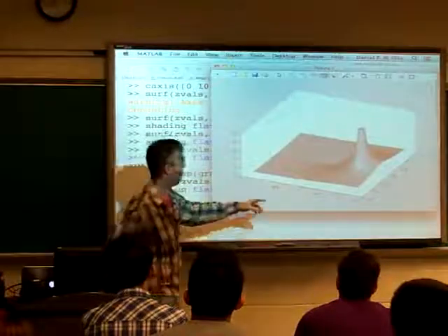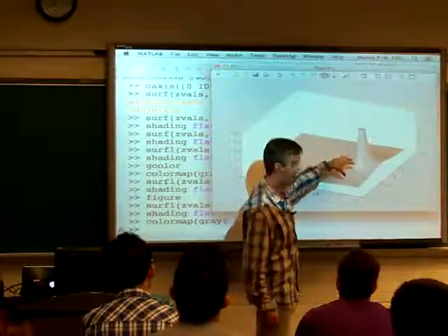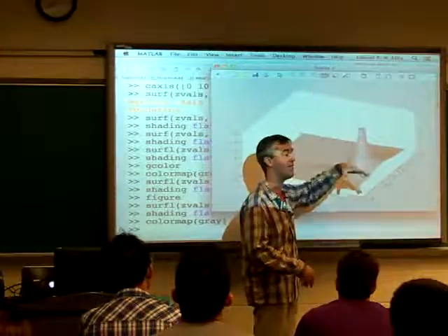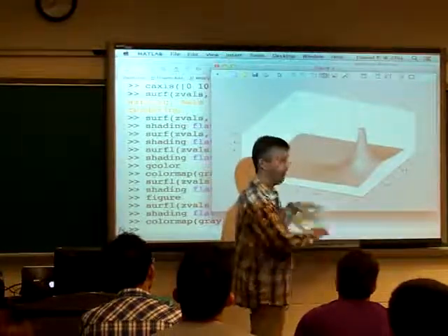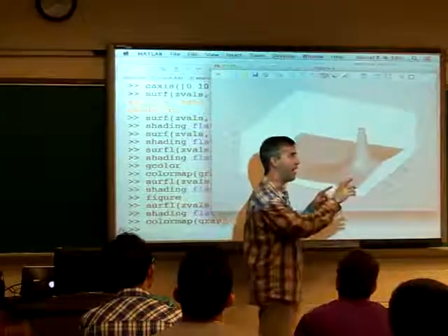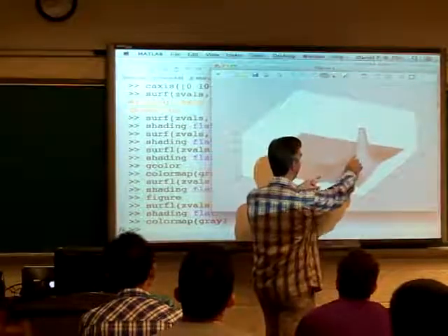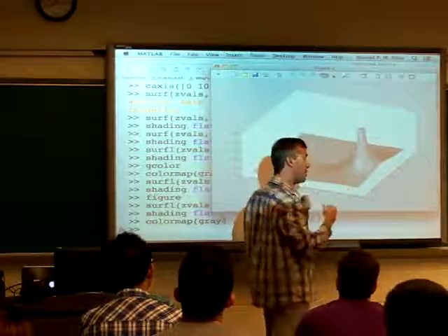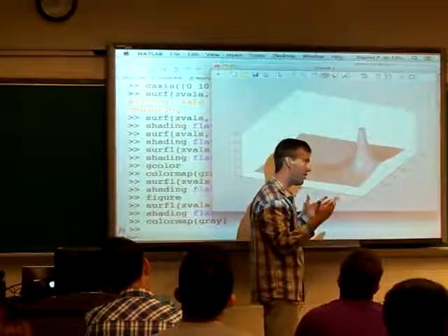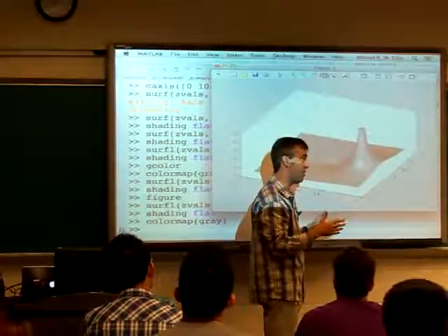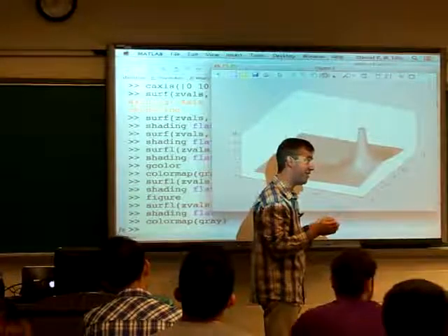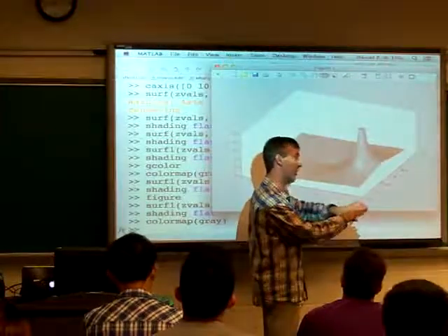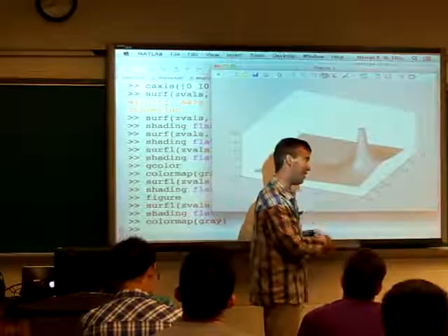It's just that outside of the region of convergence, the inner circle, 1 over 1 minus lambda z to the minus 1 continues to have a nice, continuous, well-behaved function, but the z transform blows up. And so the other function, which I haven't plotted, would be this interior part and then blowing up everywhere outside. So you see the two, g of z and h of z, or g1 of z and g2 of z, have different values. They have different values actually for every value of z. But it just happens that the convergent values match one another at the boundary, which is this z equal lambda radius.